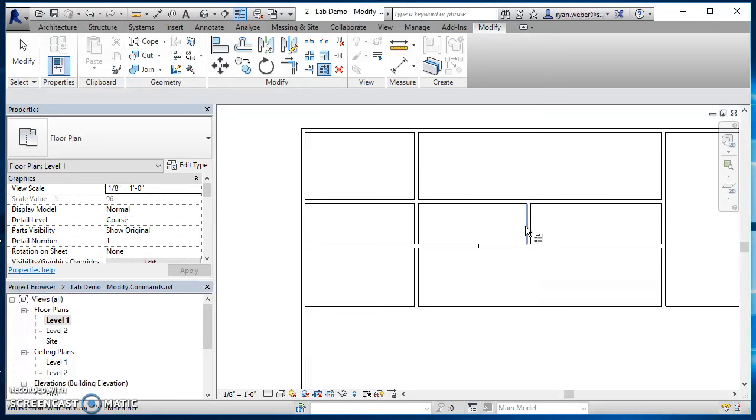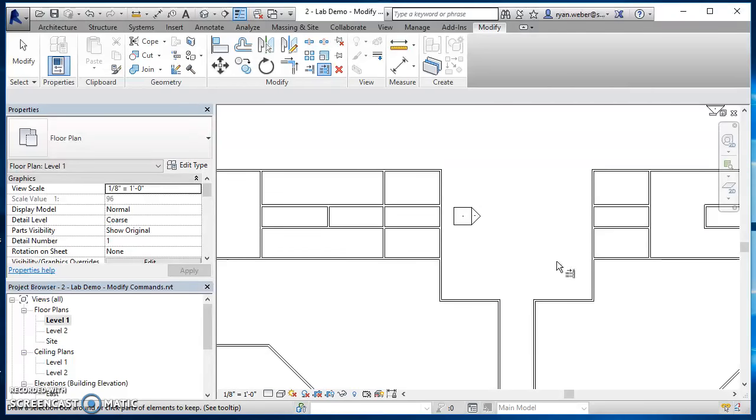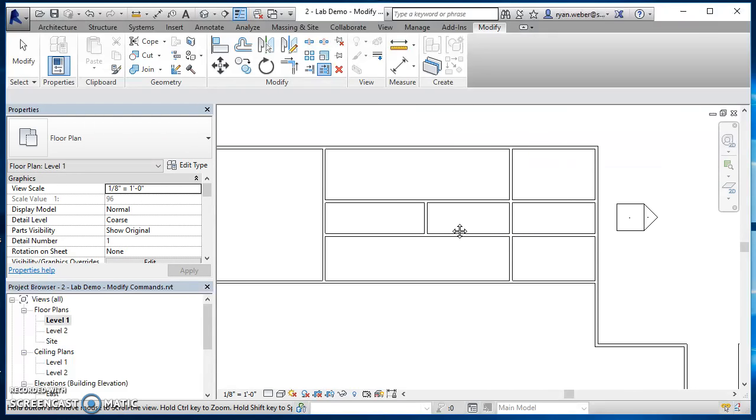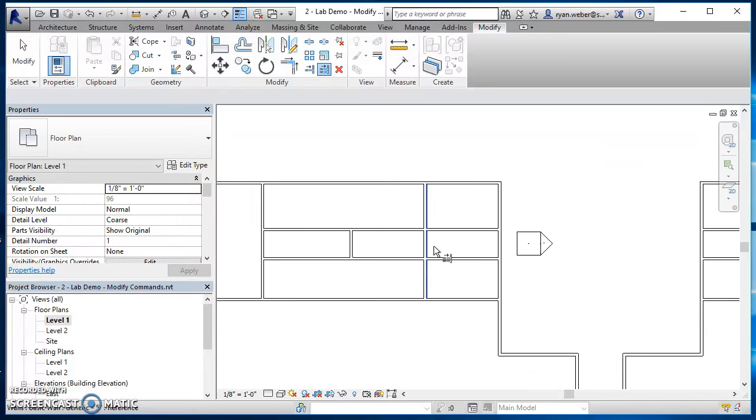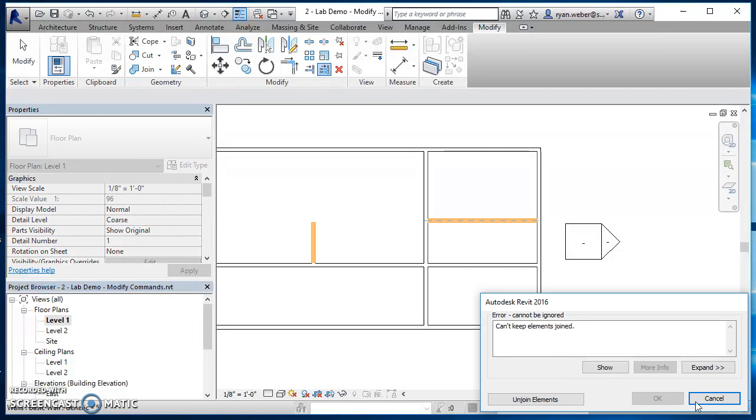So click on that, you click on your trim boundary, then you click on the parts of those walls you want to keep. And then I'm just going to click in space to clear that selection. I come over here and I can do the same thing on this other side, select my boundary, then select on the parts of the walls that I want to keep. And now I've gotten rid of that middle section of that wall. Then you can come over here on this other one and do the same thing. So trim boundary, parts of the wall I want to keep.